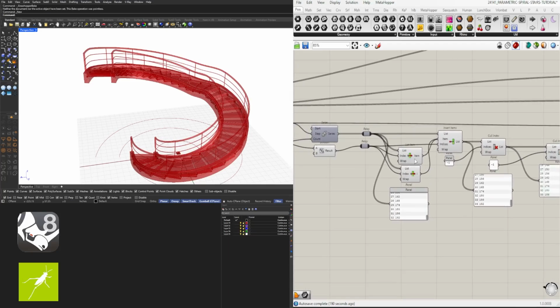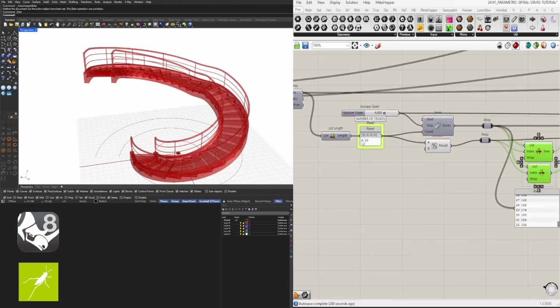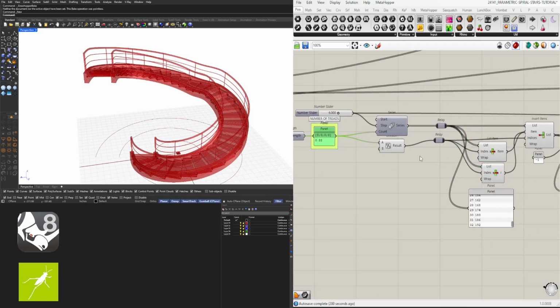And for that, we added 2 different heights that were the same for the 20th, or half of 33 here. We can also pick a specific number. So if we wanted it to be at the 20th tread rather than halfway, we can change that here.